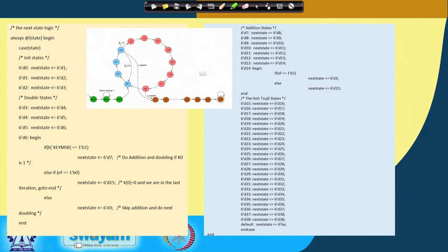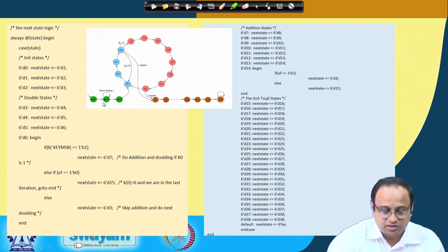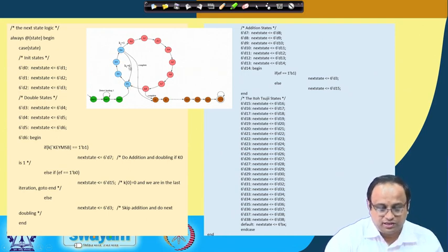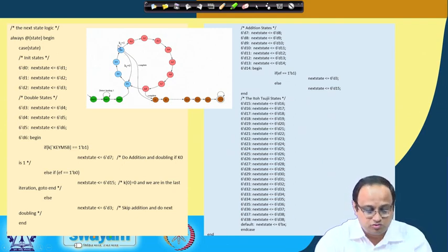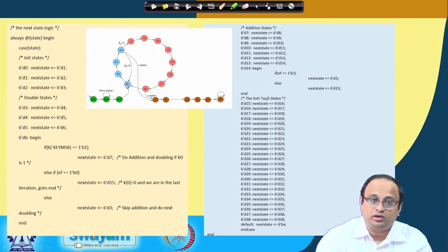Okay. So, in this entire thing, it goes into the next state depending upon your current state, except for this key logic where you have a jump. Okay. So, that essentially is this part where you have a conditional key statement, and depending upon that, from this clock cycle, you either do a doubling, and you follow a doubling with a doubling, or you go into the addition step basically. So, you either go from here to here, or you go from here to here, okay, and that depends upon your key bit. Okay.